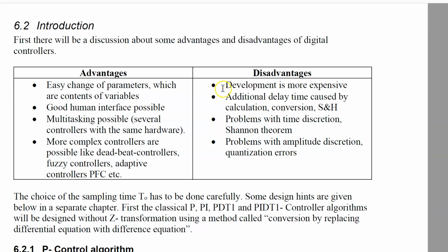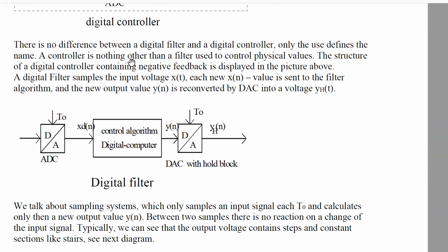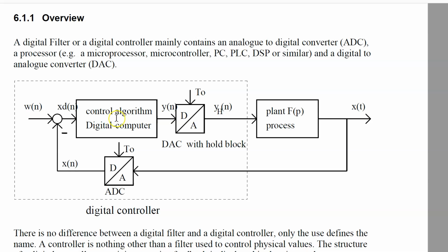First, if you compare the price, I think there is no big difference. Today, a digital controller, look back to this first picture, uses a microprocessor with ADDA converter, but this is available on one chip for some euros. So this is not really expensive. I think 30 years ago this was much more expensive, because these parts were very expensive compared with simple analog realization with operational amplifiers.